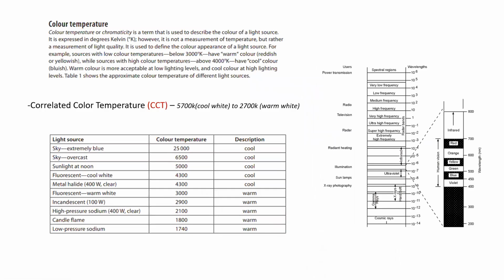The other items we have are CCT, or correlated color temperature, which is the relative feel of the light. Is it cool, warm, something like that? A lot of different types of electric discharge lighting will be in the cool area as opposed to the warm. And when we get into electric discharge, there is a choice depending on what the coating is and what we have on the tubes. It can be all sorts of different types of coloring. So it's important that when you're relamping, all of the tubes you replace with are the same CCT rating. Otherwise, you end up with a patchwork array at the very end of the job.